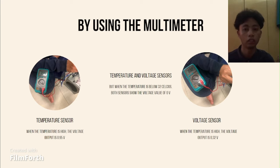So next, the right side is for the voltage sensor. The voltage sensor also has a 3-pin output. At the middle is the positive, the left side is the negative, and the right side is for the sensing pin. So the sensing pin we will connect to the positive terminal of the multimeter, and the negative from the multimeter we connect to the negative of the sensor, and we obtain 0.32 volt.